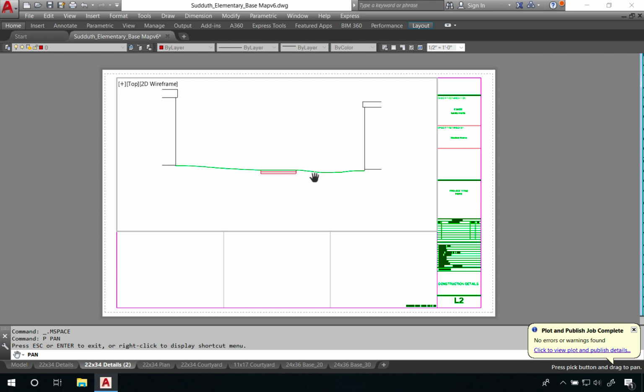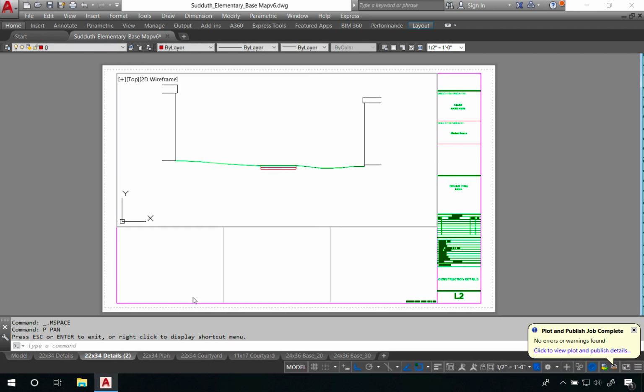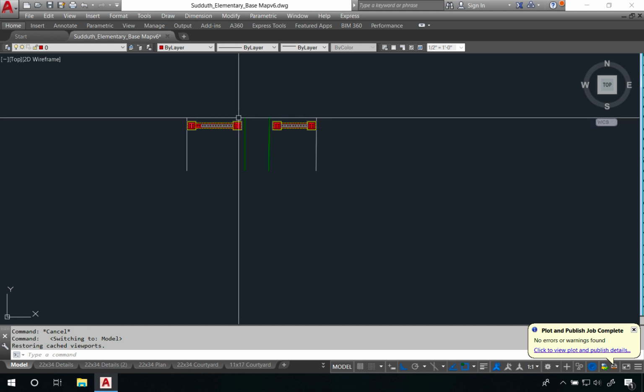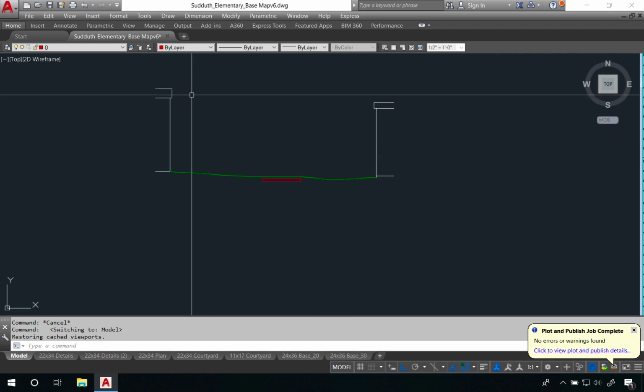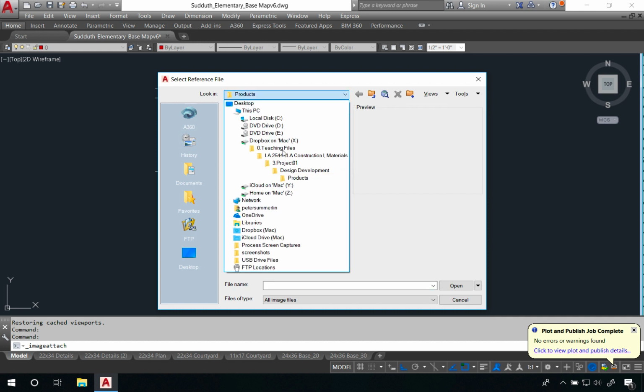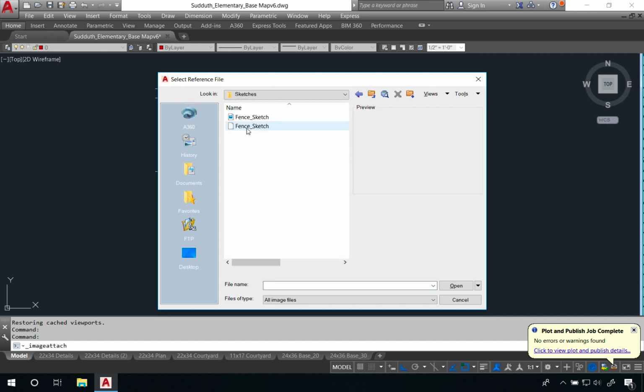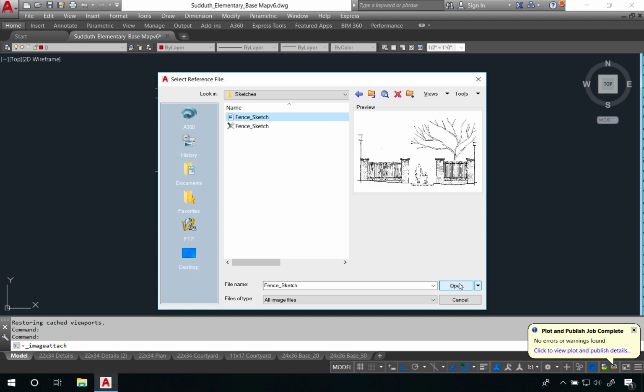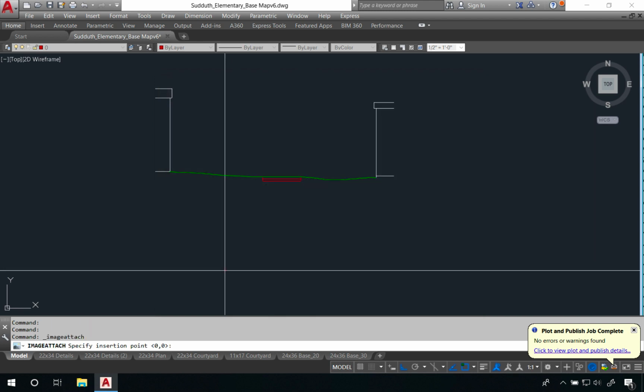Once that line work is actually sketched, we can scan that line work in and bring that into AutoCAD as a JPEG. We'll do that here in Model Space. We'll come back to Model Space, we'll zoom up to our line work, we'll go to Insert, Raster Image Reference. We'll zoom out to our sketches and this JPEG right here and bring it into our drawing.